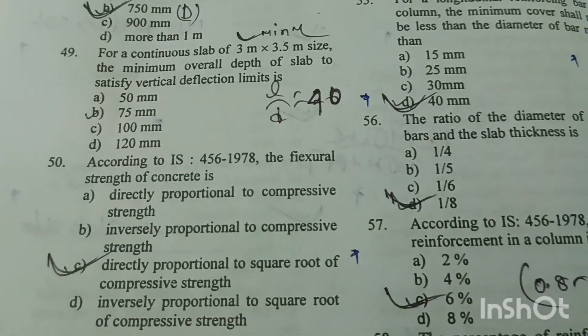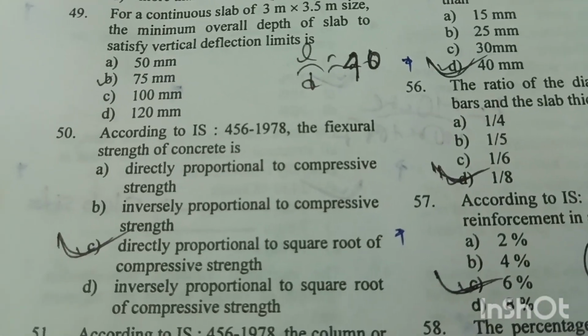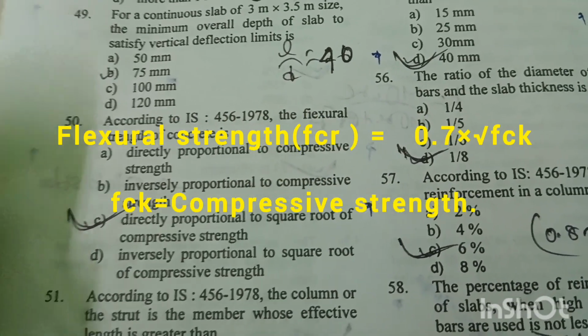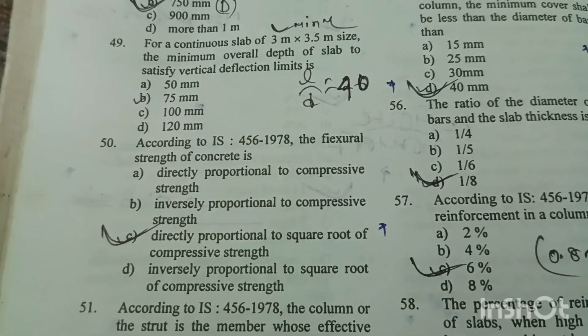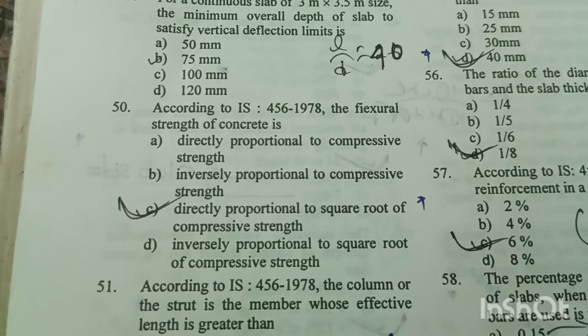Question number 50. According to IS 456 1978, the flexural strength of concrete is directly proportional to the square root of the compressive strength. Option C is right answer, because we know flexural strength FCR equal to 0.7 into root over of FCK, where FCK is the compressive strength of concrete.